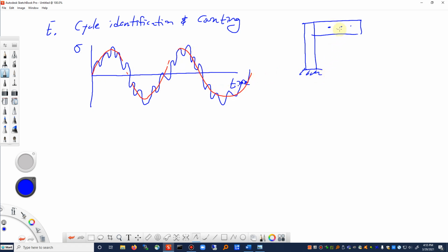At the same time, maybe there's some sort of natural frequency thing happening, or maybe the gusty wind is ebbing and flowing, but on top of that is a lot of very fast back and forth. Sometimes you see these signs whip back and forth and almost vibrate. That higher frequency may cause this superimposed oscillation, so that's where all these little ups and downs, these little squiggles, would come from. All right, so do we have one big cycle? Do we have a whole bunch of little cycles? Well, in truth, we actually have both.